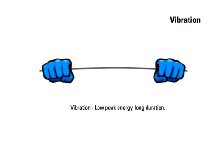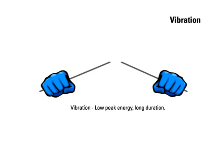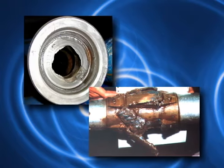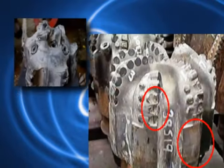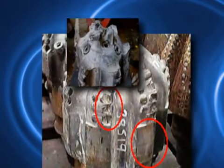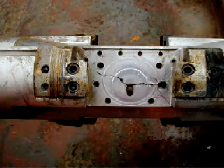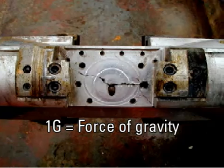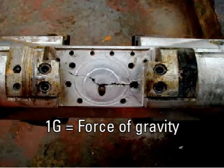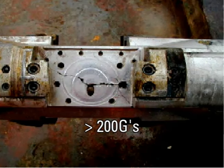Vibrations can result from the shocks. Rapid and continuous vibrations result in fatiguing of the drill string connections to the point of twisting off. This is why many drill string failures are the result of cumulative fatigue due to vibration and have regular inspection periods. Shocks are measured in G's by an accelerometer. 1 G equals the force of gravity. Shock magnitudes registered via downhole tools can exceed 200 G's.